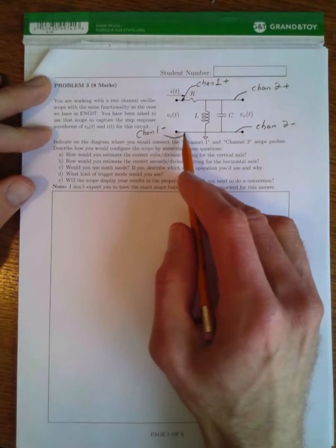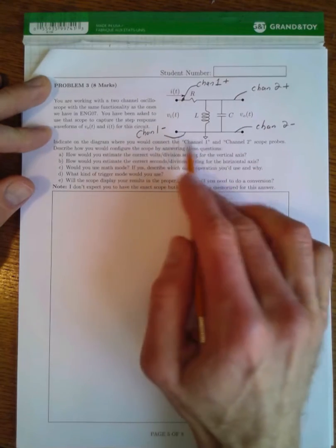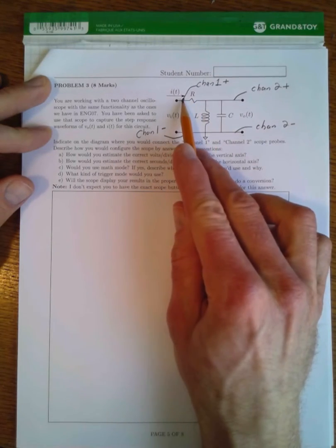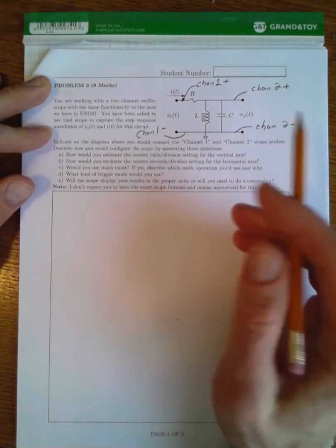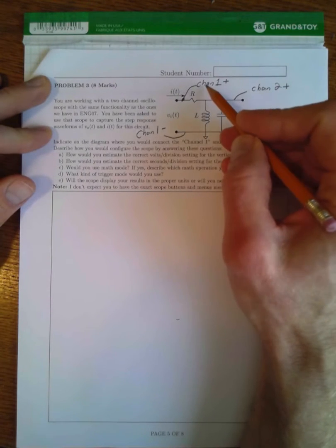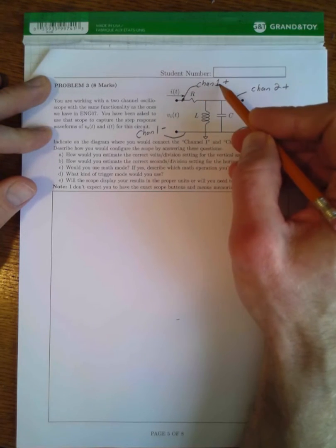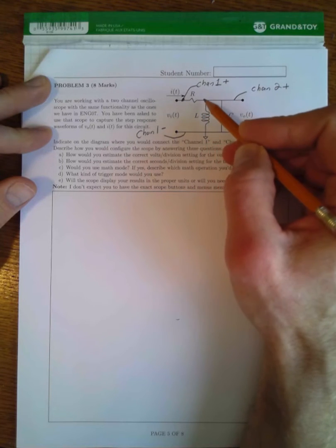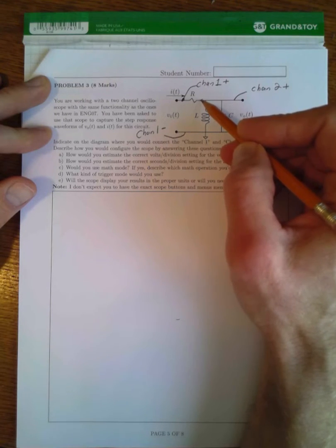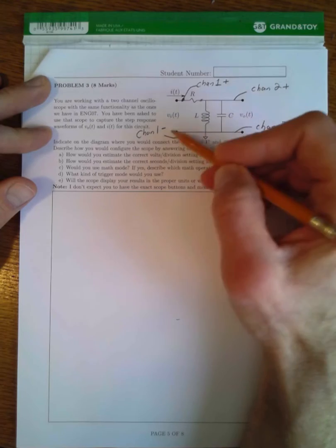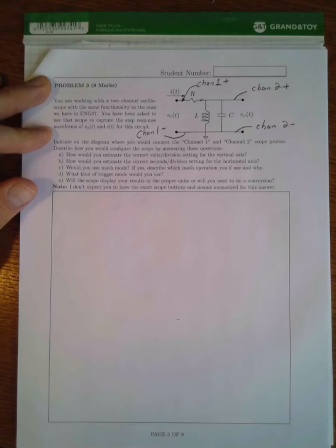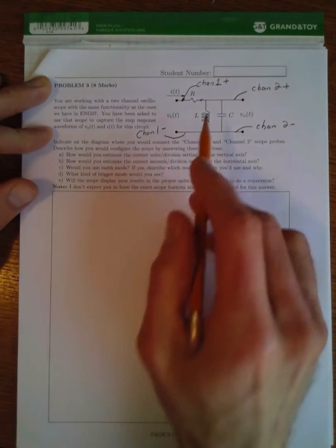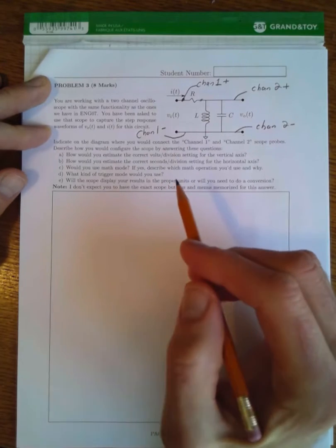Oh, also I should say, for this scope connection part of the question, some people only indicated one connection, which I understood as the positive part, and that was fine. However, a few people did put, for example, the positive part of one scope probe on the left-hand side of the resistor and the negative part of the scope probe on the right-hand side of the resistor. And what that actually does is connect this part of the circuit to ground, because the negative part of the scope probe is actually connected to the ground of the oscilloscope, and that will short out the circuit. So I took marks off for that.